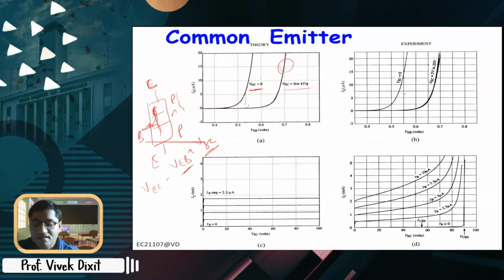So that's why you see this thing here. And again, it depends on the reverse bias, but the effect is minimal here. And then IC versus VCE, right? We expected it to be constant with VCE, but in effect, it actually linearly increases in one region.